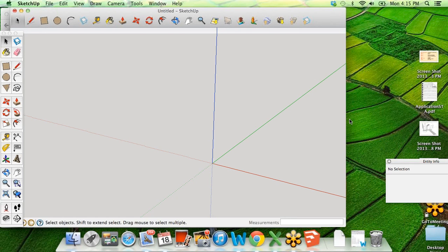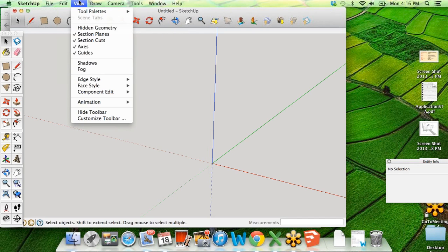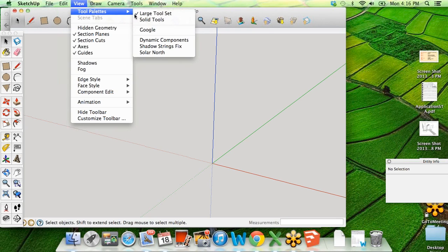I have one question here. Hey, Jonathan, what's your question? I was wondering how you get the bar on the side that has the other stuff. Oh, that's a great question. I will actually show you guys that in a little bit. But I can show you now that you asked. I'm going to mute you though because I'm hearing a recording of my own voice. You go into Tools. Wait, no, I'm sorry. View, Tool Palettes, the large tool set, and that will give you everything.